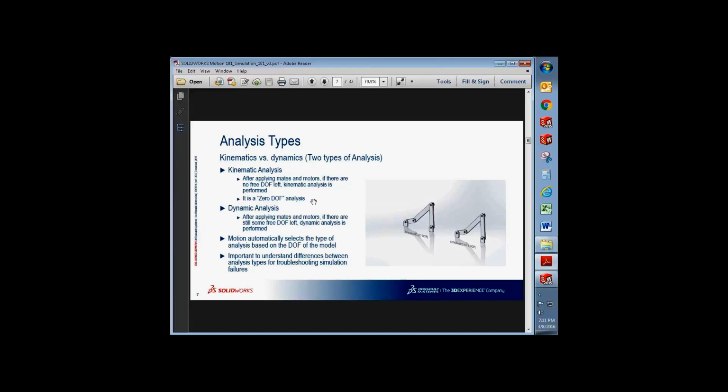So the way you can check this is we have a degree of freedom calculator in our software, where you can say, okay, how many degrees of freedom does this mechanism have? And if it's greater than 1, which means there's more than one solution for your problem. And if it is 0 or negative, if it's 0, you're great, but if it's negative, you have redundancy problems, and I'll come to that as well.